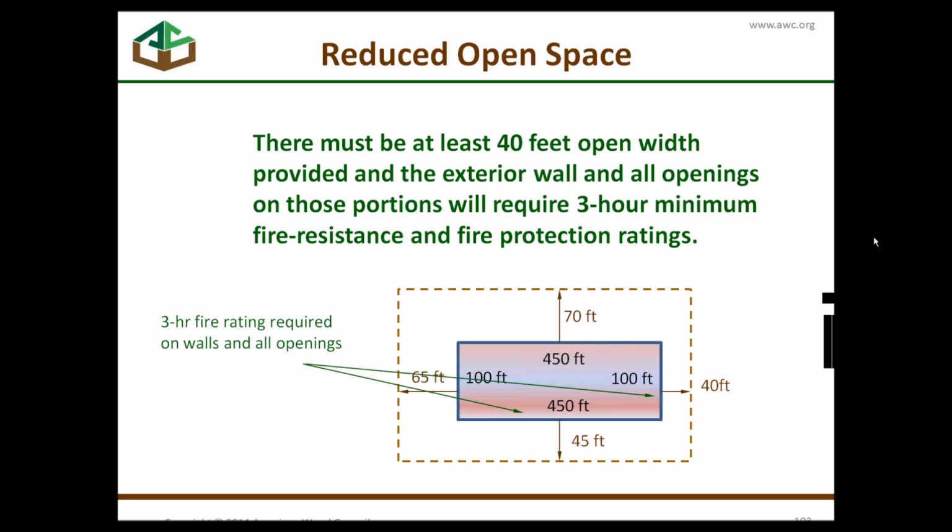So if you have a 5A building, it means it's wood frame typically, but the walls, floors, and roof are rated for 1 hour fire resistance, and no, your openings would not be required to be protected in those rated walls, floors, and ceilings unless the code required them to be rated for purposes of some type of separation.